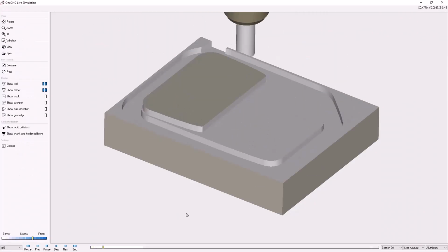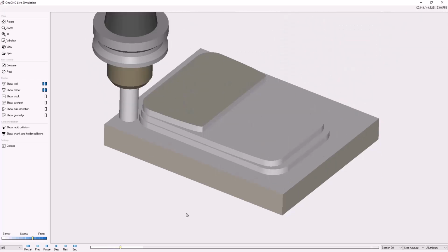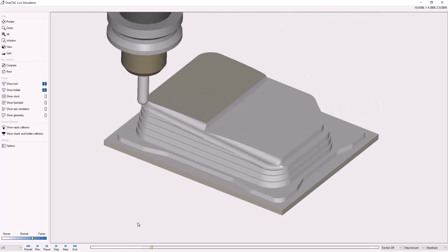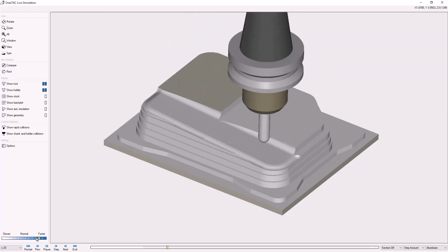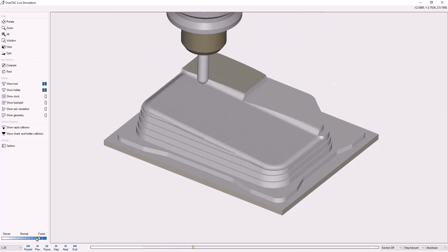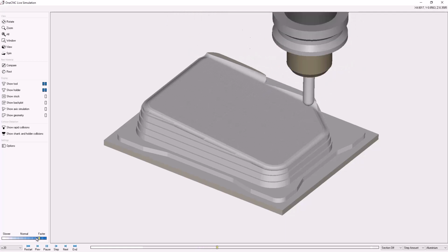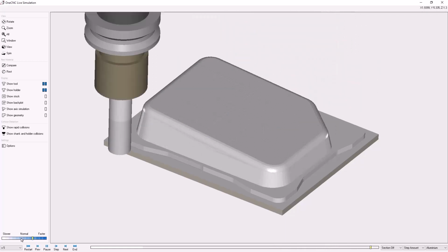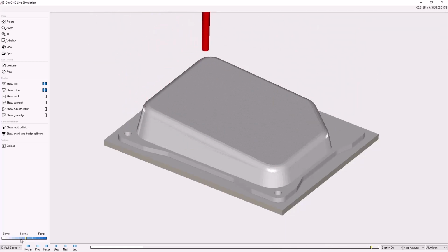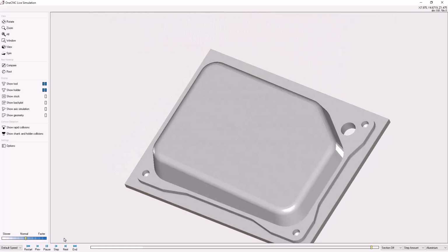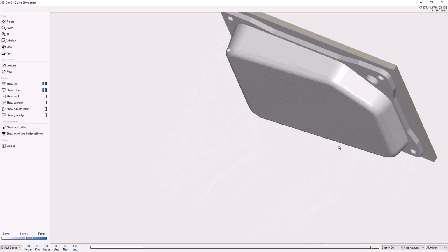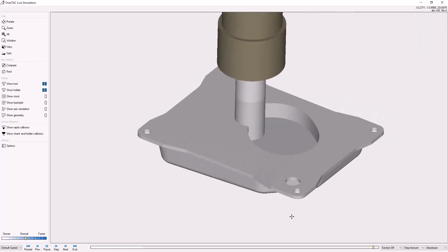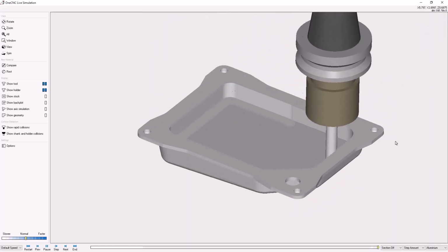All right, so here we go. Here is the toolpath simulation for the first side. This is our roughing operation. Going to change tools to the ball end mill. Going to speed this up a little bit. We're machining the top of that boss. Then we're going to use the Z-level finish command to finish the sides of the boss. I'm going to slow this down right about here. Change tools to a taper tool. Profile the boss. Now we're drilling the holes. This is simulating us repositioning the part and then placing the part in soft jaws. There's our facing operation, our roughing operation, and there's our finish profile operation.